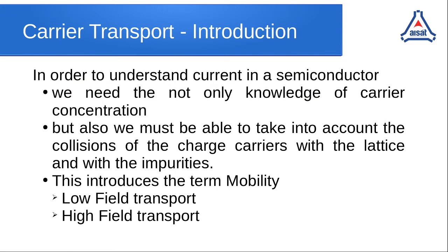Carrier transport. Why are we interested in carrier transport? This is for understanding how current flows in a semiconductor. In order to understand current in a semiconductor, we need not only the knowledge of carrier concentration that we had seen in the first module, we must also be able to take into account the collisions of charge carriers with the lattice or the atoms and also with the impurities inside the semiconductor.